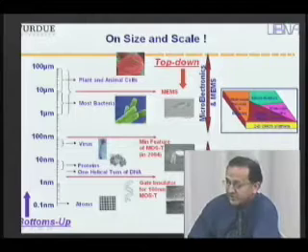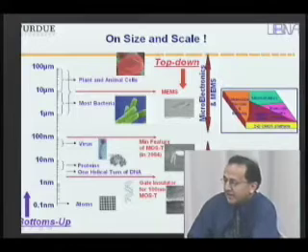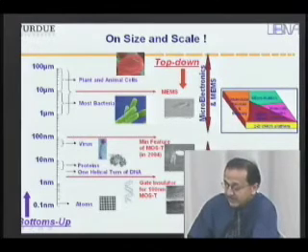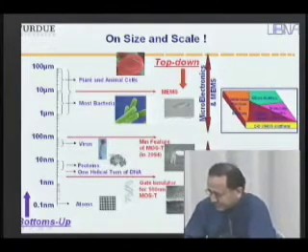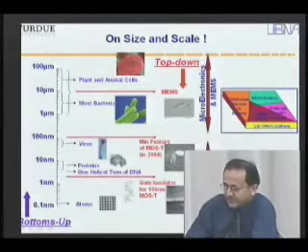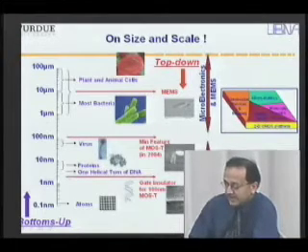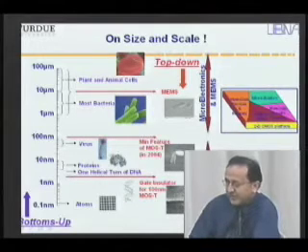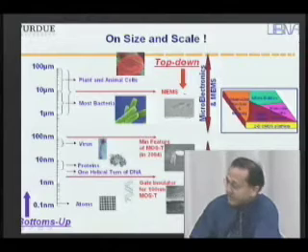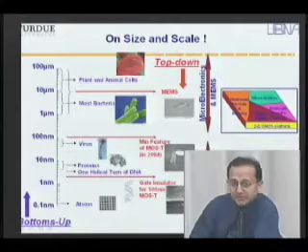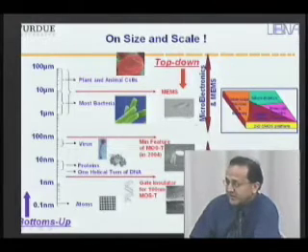This is a picture of a polysilicon gate with nitride spacers. And then one of the gate insulators, which is one of the most critical elements of a MOSFET for these 100 nanometer devices, is something in the order of 2 to 3 nanometers. So we can today make these structures that are ranging anywhere from 100 microns down to a few nanometers with great precision and accuracy. And this provides us an opportunity to really merge these two worlds, the biological world and this non-biological world, to make integrated sensors and devices.